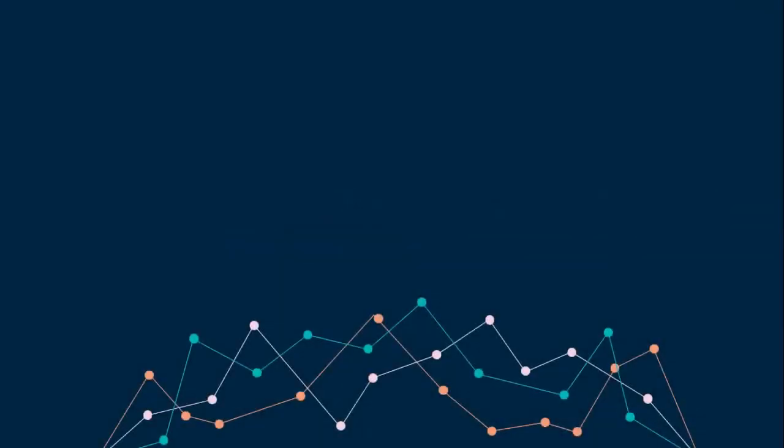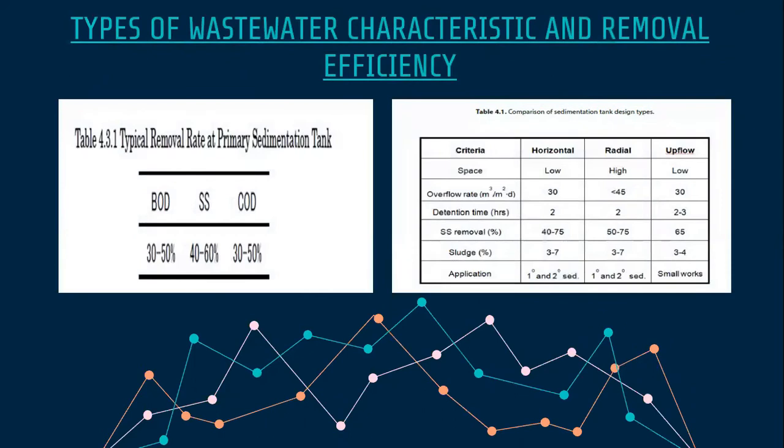Okay, so now I will explain the sedimentation process from its characteristics. Both tables on the screen show types of wastewater characteristics or pollutant characteristics and their removal efficiency. From the left side, the first table is from the Design Standard for Municipal Wastewater Treatment Plants by the Japan Sewage Works Association. The sedimentation tank could remove 30 to 50% BOD pollutant, 40 to 60% of settleable SS pollutant, and 30 to 50% COD pollutant.